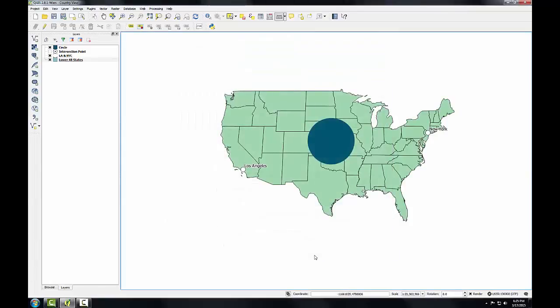So this is certainly a distinct improvement in shape, but there's still some skewing. The Eckert 4 projection is primarily used for mapping the entire world. So for mapping large countries at mid-latitudes, such as the US, other projections are more appropriate. The Lambert azimuthal, Albers equal area, and Lambert conformal conic are all examples of suitable projections for mapping the entire US. Because it has two standard parallels, the Albers equal area projection is particularly good for larger countries with a significant east-west extent like the US.